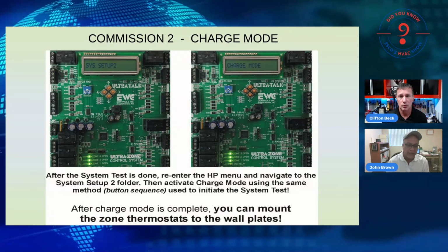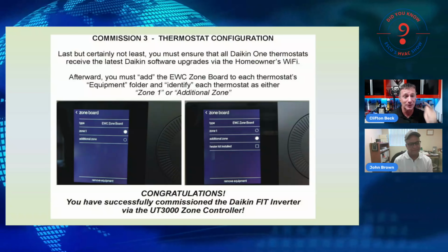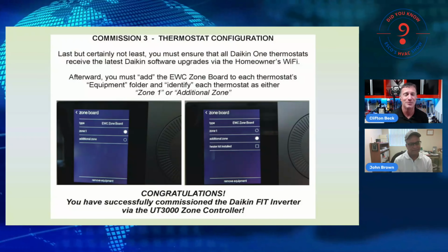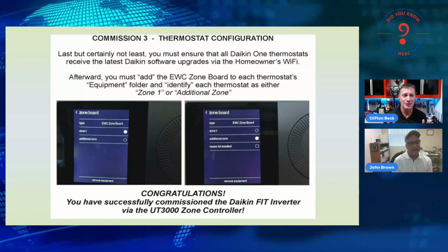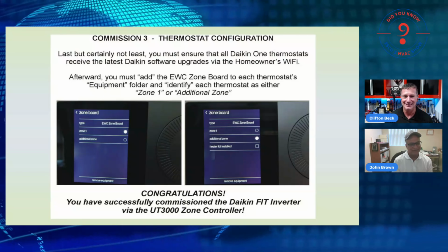Wow. Okay. So we have commissioned a piece of equipment. We're talking a communicating inverter outdoor unit. Say we've got it connected to the highest capacity, 97% modulating gas furnace. We have our communicating zone control board, no thermostats connected. We have done a complete commissioning. We've done a complete system charge, all without any thermostats connected. Love it.